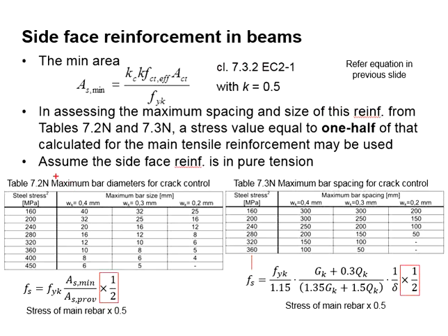As for the calculations for the maximum bar diameter and maximum bar spacing, if you observe the formulas, you will see that the estimated stress is half of those equations that are used for the calculations of the main reinforcement.